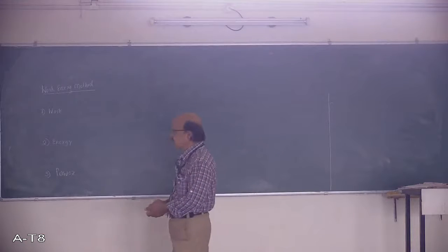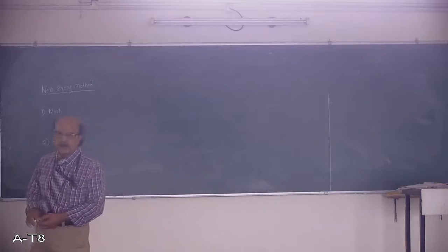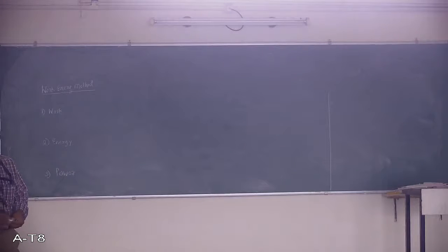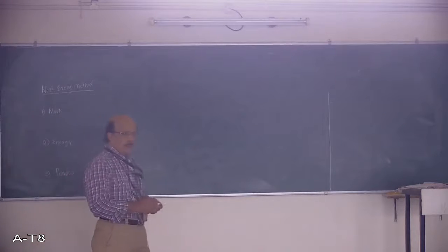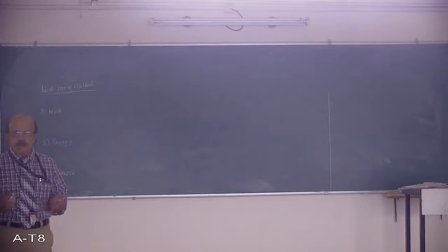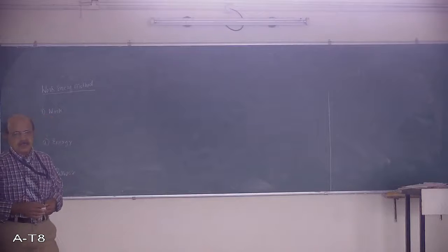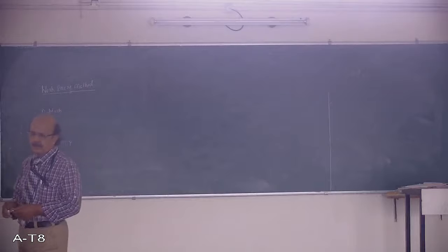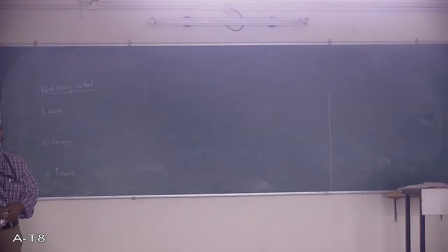for the work energy equation, and using that equation we will be able to solve most of the problems. One thing is that the D'Alembert principle can also be used to solve these problems, but if they are related with acceleration, if you want to determine the acceleration, distance and other things, then we can go for that principle and our problems will be very easily solved. If they are associated with velocity and time and other things, then you should go for the work energy method, the work energy equation, so that the problem can be very easily solved.